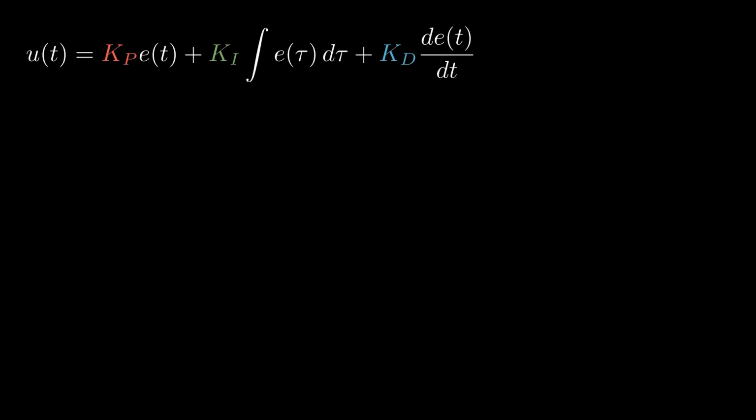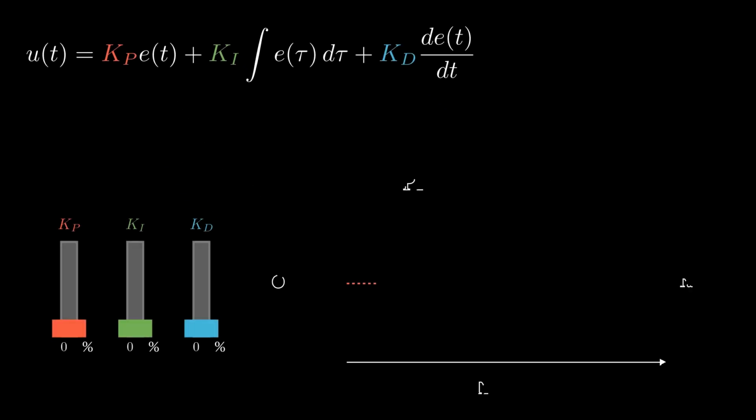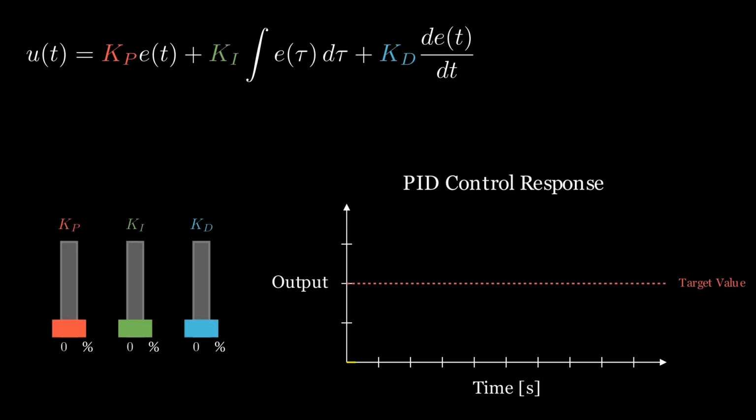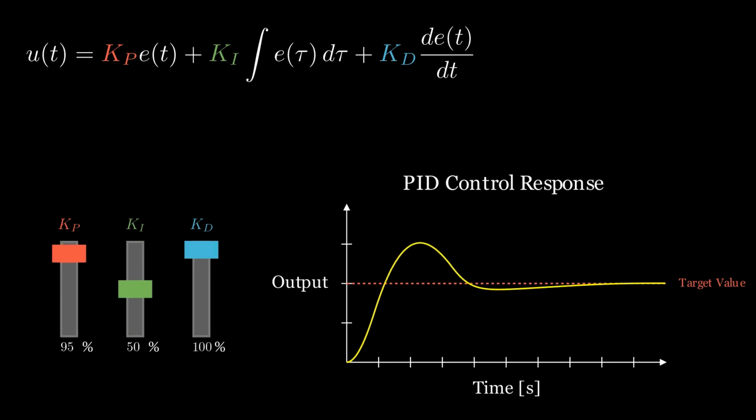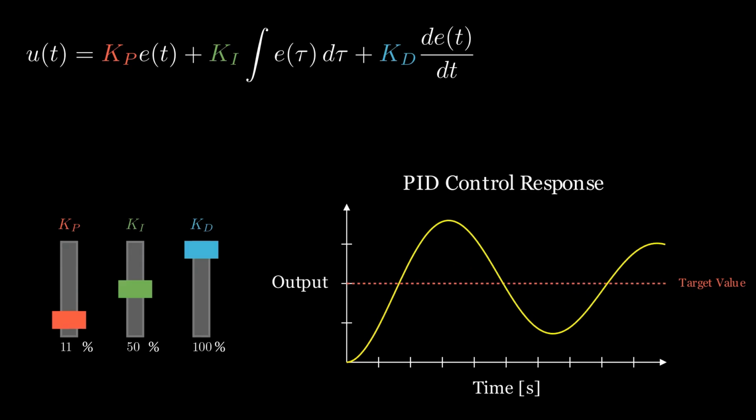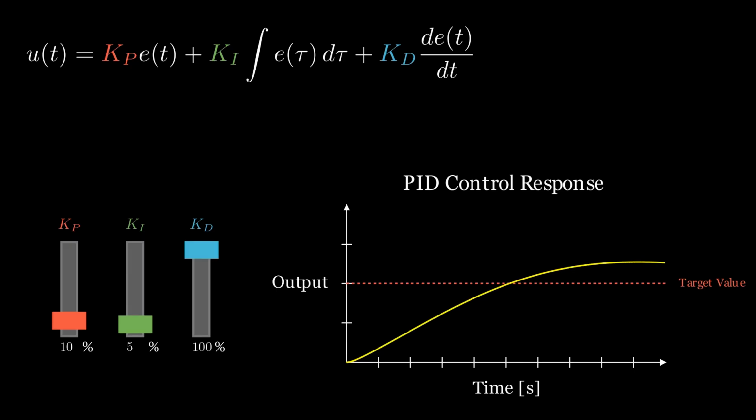Balancing them seems difficult. Exactly right. Tuning is often based on empirical rules. If you increase the P gain to speed up response, it becomes unstable. You use D gain to suppress that. If you add too much I gain for precision, the response slows down or becomes unstable, and D gain is sensitive to noise. There are always trade-offs. This isn't just a PID issue, it's a challenge inherent to all control engineering.